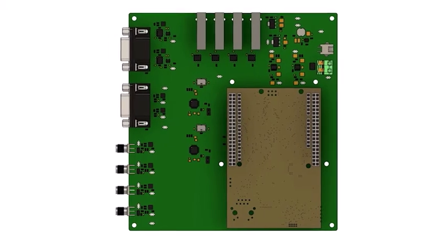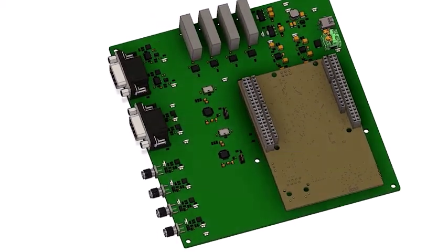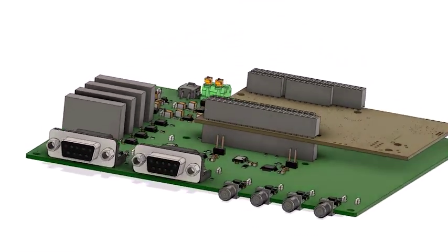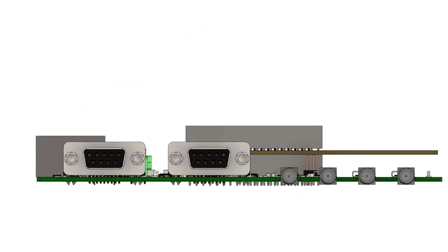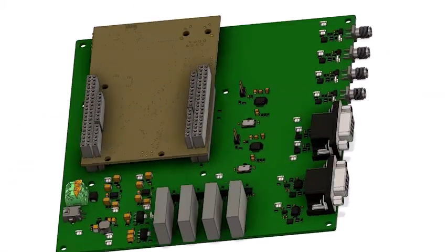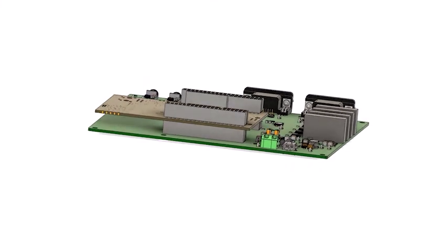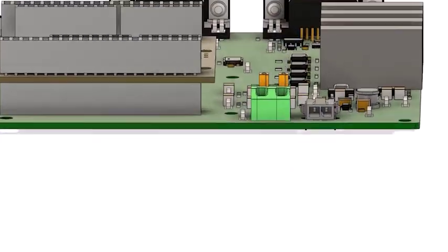Our circuit board is a 6-layer circuit board. The IEPE sensors are connected with SMA connectors on the bottom left, while the current loop and full bridge use standard DB9 connectors on the top left. The thermocouples use specialized connectors shown in the top center. Power enters the board from the connectors on the top right.